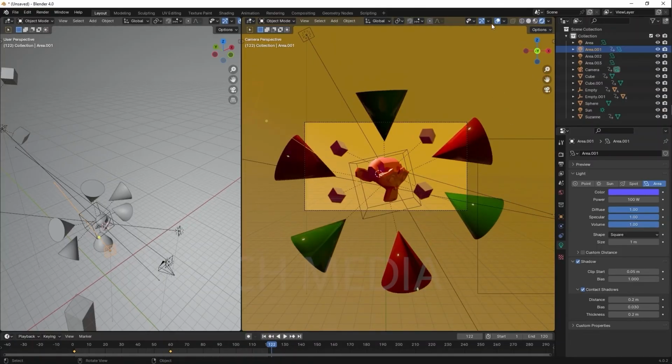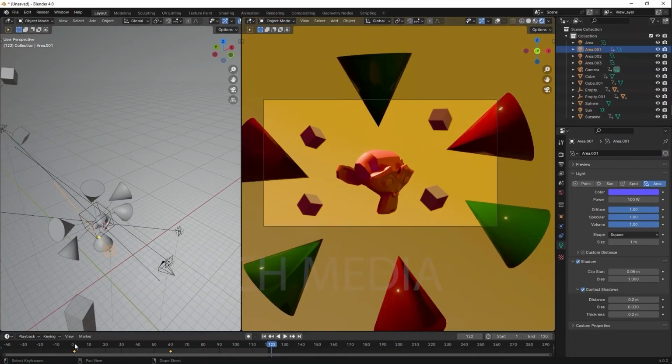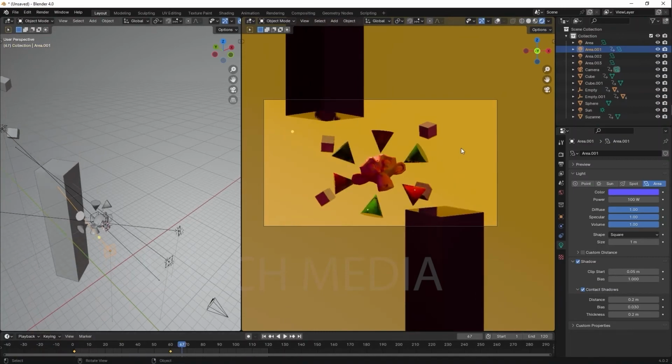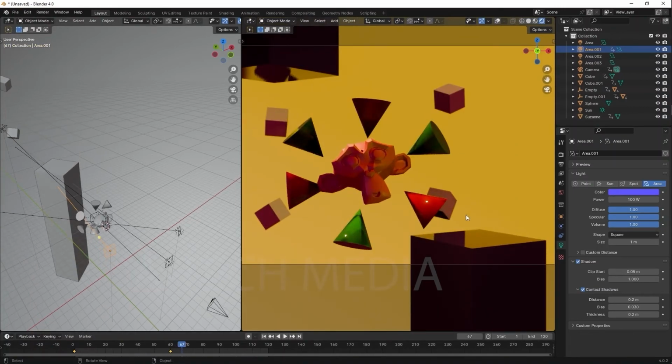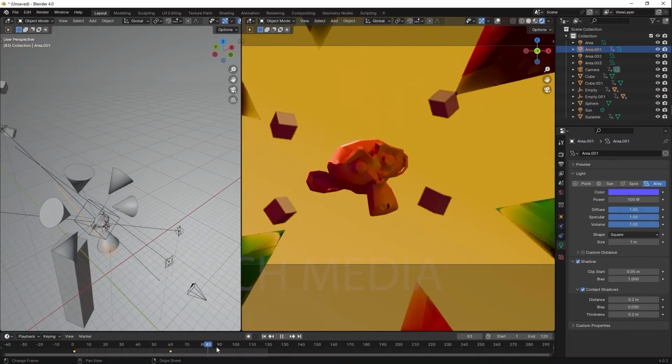So, I've said cool several times, and yeah, that is animation. It's basically doing the exact same thing over and over again, which is just add a keyframe at the start of your change to record the object before it's animating, before the change starts, then add an end keyframe, which is the end of your major change, and Blender interpolates between them.